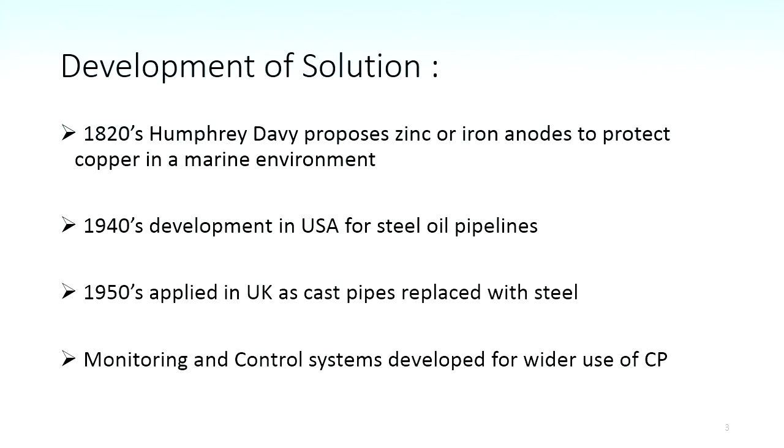So, we've got these pipes. They're exposed to environments that are aqueous at times. They may have microbes in them. They may have stresses applied to them because of the pipe pressure and so on. So you might get cracking, you might get localized attack, coating defects. There are lots of things happening. How do we try and limit the amount of corrosion?